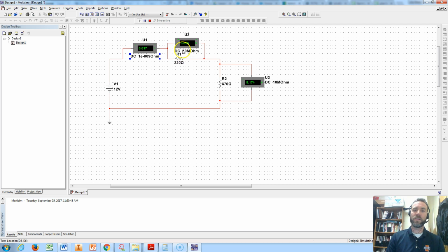It knows that it's got 10 million ohms in parallel right there, and it can do the math about what's going around through the other ones to give you this. And it's got just some very tiny, 9 nanoohms of resistance through here, so it's not removing really any current, but it's able to tell us how much current is going through there.